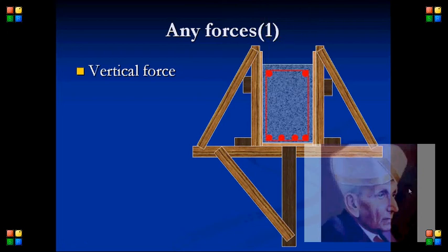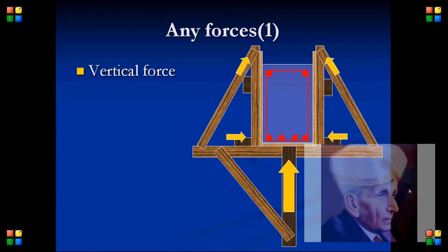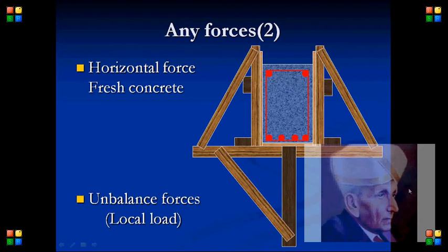Forces: 1. Vertical forces. Dead load of concrete, steel, and the formwork itself. Live load of workers, equipment and others, and impact load.